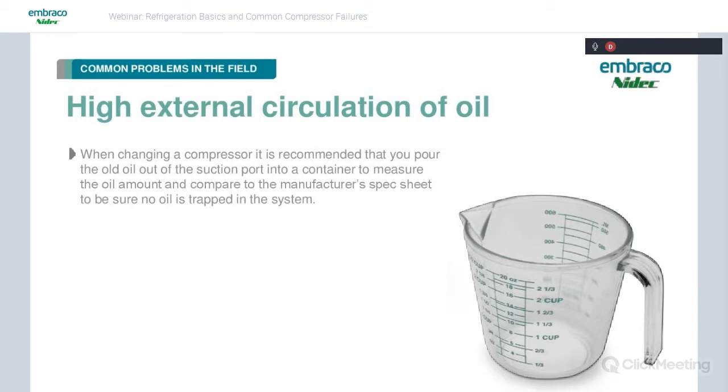What's going to happen is when you put the new compressor in and you get normal pressures going again, all of a sudden a big old slug of oil is going to come back to the compressor and hit the valves, break the valves, or overfill the crankcase and cause problems. It is recommended to pour the oil into a container and measure it and make sure it's within plus or minus 2% of what's listed on the spec sheet.